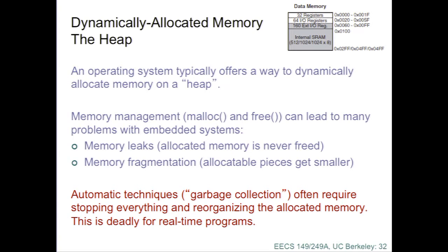Those are usually part of an operating system. But in an embedded system context, often you have a very small runtime kernel, and the runtime kernel may only provide malloc and free and nothing else, okay? It can be that small, all right?